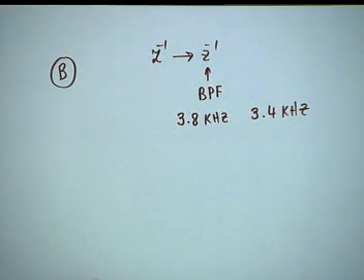notice that we are not touching the stop band at all. Whatever stop band edges come has to be accepted. Digital to digital transformation may not always work, because by transformation you may not get the desired stop band. We are hoping that this will be met, all right. Then only digital to digital transformation is useful, not otherwise, because we are not touching the stop band. Agreed? So, it may be possible that it may undersatisfy the stop band. That's right. Then you cannot use this. So, then what is the method of checking it that it is satisfying or not? You have to plot. There is no other way.